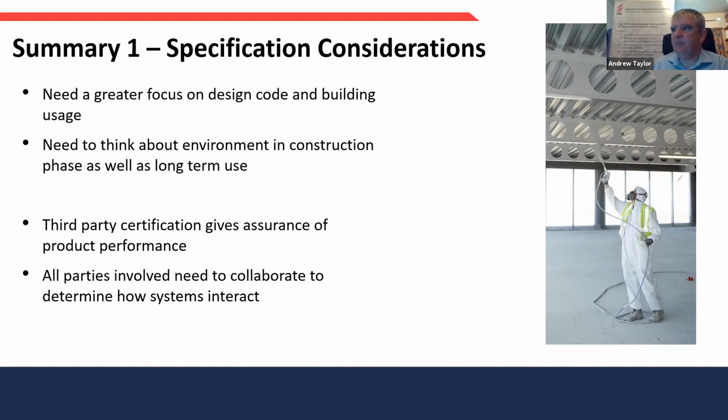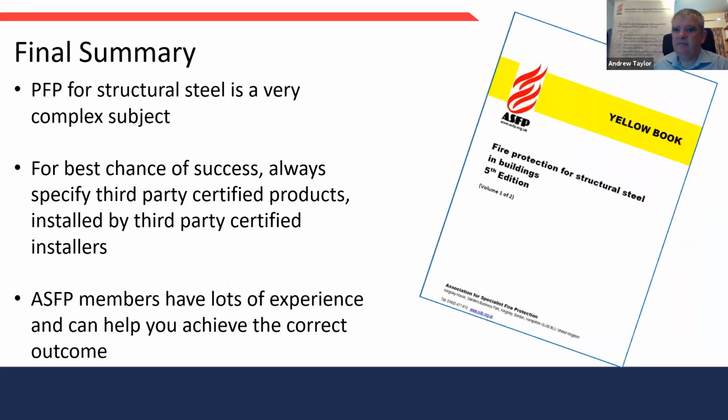Okay, but in final summary, and you've seen this before, PFP for structural steel and indeed any structure is a complicated subject. For best chance of success, always specify third-party certified products installed by third-party certified installers, and there's lots of information out there on the ASFP website to help you.